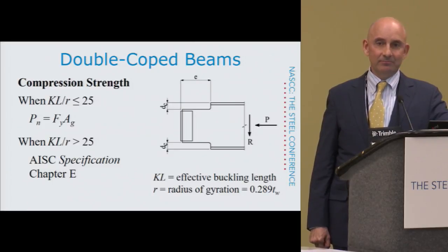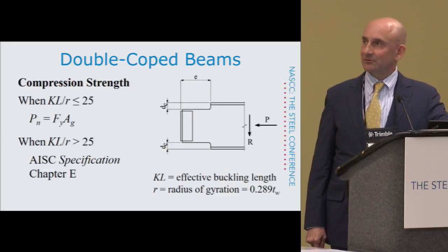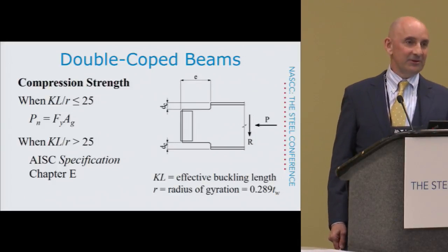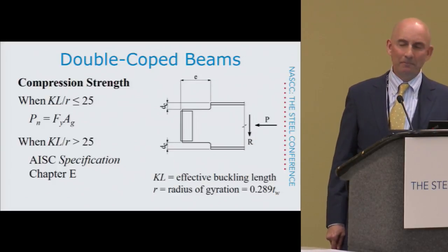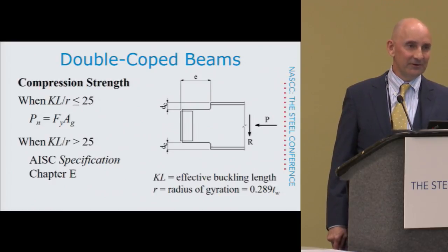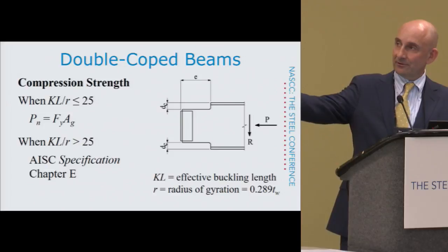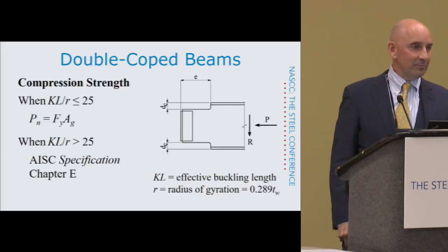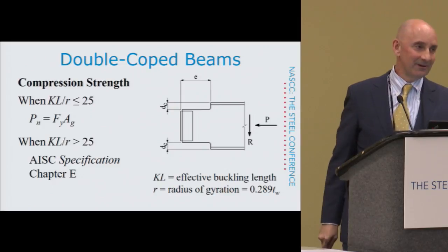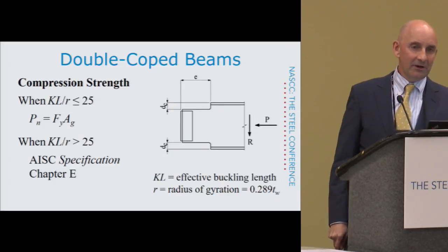And of course, I can't give you a number. Typically, I would use 0.5 in that case, the theoretical value. But that's only if you have, say, a W16x26 with a quarter-inch thick web, and then you've got 5/16 clip angles, a double clip angle connection to restrain that end, and let's say that's braced by decking up here so it can't translate, then yeah, I would use K equals 0.5.